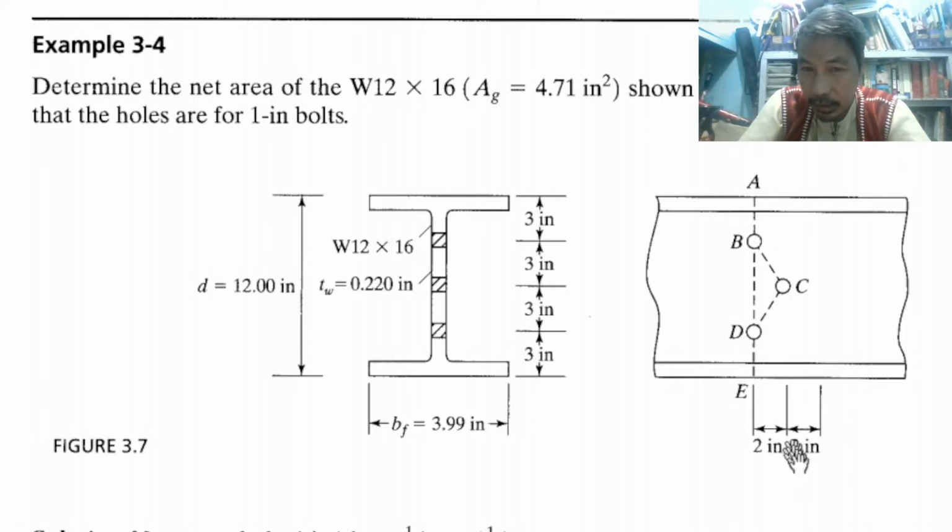So this is about excessive use of dimensions. This is a dimension for what? Nothing. So we only need 2 inches here in order to clarify that the lateral distance between the centers of the holes is 2 inches. What is the next 2 inches? There's nothing about it. So unlike this one, all of these are required.